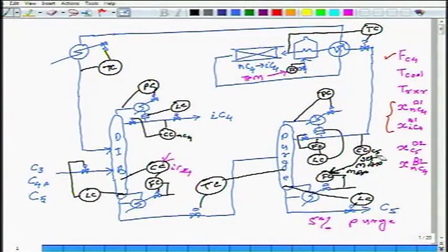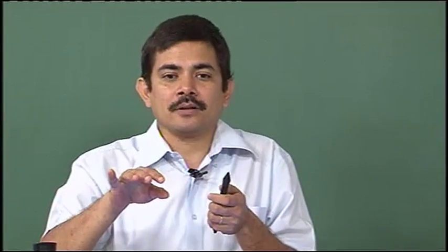That's clear to me. How to control it? I don't do it this way, because boil up becomes saturated. I do it the other way. When it is not saturated, the boil up, what does it control? It controls the C5 recirculating around. That's it. These decisions have to be thought through. They are coming from what becomes active, what doesn't become active.